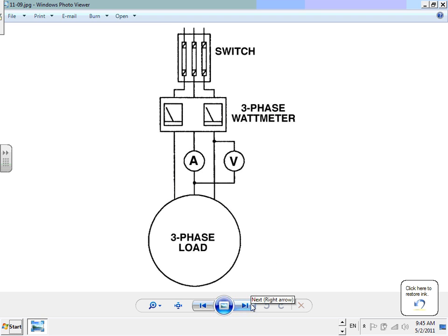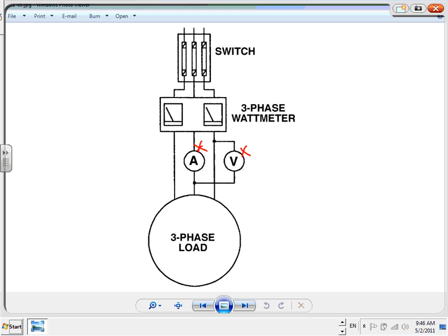If you have a three-phase load, for motors, I'm going to show you two ways of correcting power factor. To correct the power factor for a motor, you need to know the amps and the voltage. If you remember, the apparent power equals 1.73 times I times V. That's my apparent power. And the true power for a motor, everybody knows what that is.